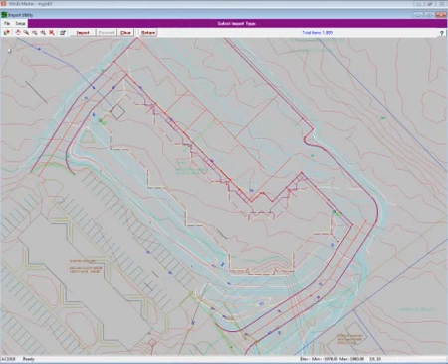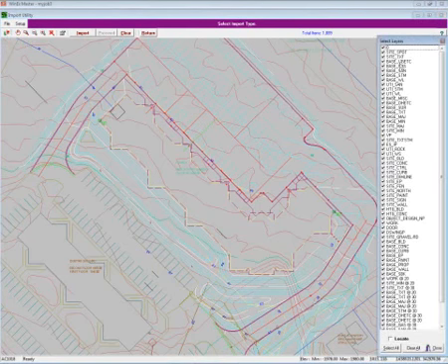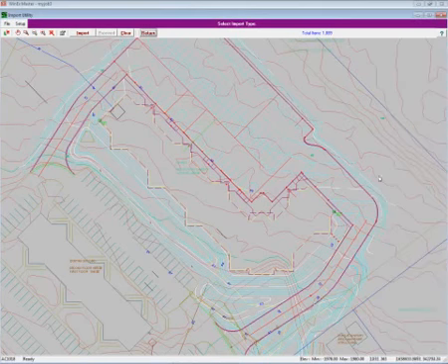Now, if you'd like, you can click on the Layers button and see how the engineer, or if the engineer wasn't in between you and the architect, how the architect set up the layers in this CAD file. And what I normally recommend is clearing everything, and then just clicking on each one so you can see how he laid it out. But I'm very familiar with this job, so I'm going to close that window, and I'm going to tell the software that I want to begin importing immediately.